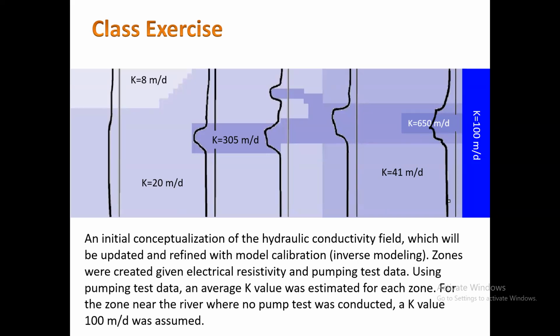Whether these boundaries, so for example, recharge, that will be a source term because I'm adding water to my system, right? While a pumping well, that would be what? Source or sink term? Like a pumping well, would that be a source or a sink term? Sink term, yes. Recharge, that's a source term because I'm adding water Q to my system. Here, that's a sink because I'm extracting water from the system.